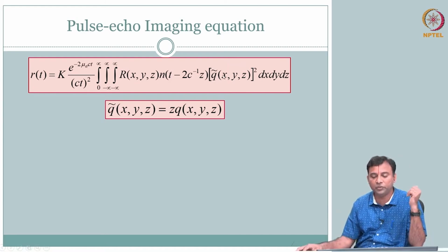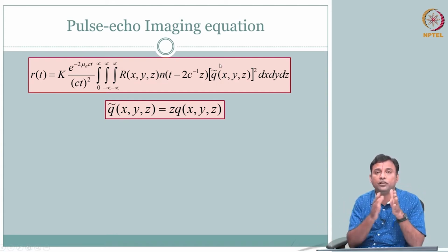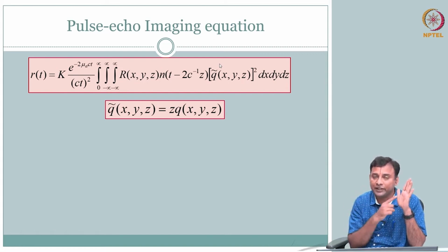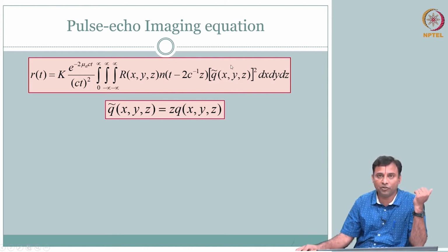We played with this q, right? In fact, we told that in the far field it is essentially a Fourier transform of your transducer shape. So if it is a circular disc, then you get a Bessel function. If you get a rectangular disc, right, rectangular shape will give you sinc in 2 dimensions. So this is your directivity. We talked about main lobe, side lobe. So this is your beam pattern, if you will.